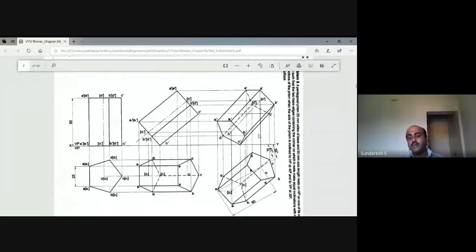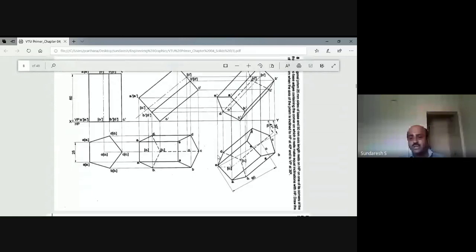If any portion, even a small portion, goes beyond or above the XY line, then the third position will be considered wrong. Therefore, while you are doing solids, take a convenient distance below the XY line, draw one parallel line to the XY line, and from there you can measure the angle. Make sure the solid does not go above the XY line.